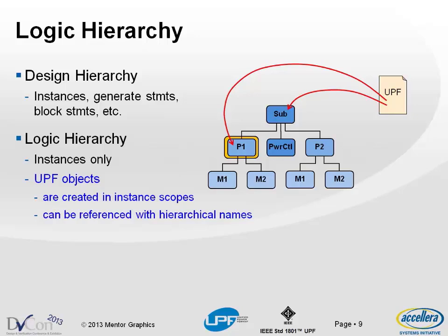And the important point here is that depending upon where you created things, the name that you use to reference that object is going to be declared in that location. It has to not conflict with names that are already there, obviously. And also, just like any other name that's defined in your HDL, you can refer to that by that name in that location, or in general, with a hierarchical name that goes down to that location, and then you refer to that object. So think of UPF as essentially overlaying names on top of your logical hierarchy.